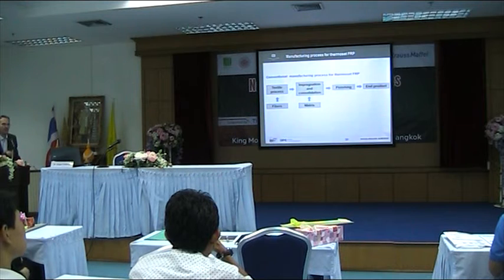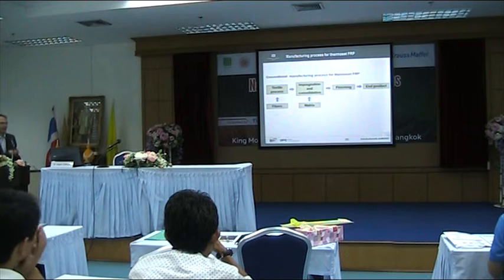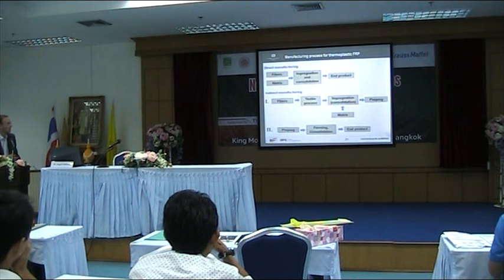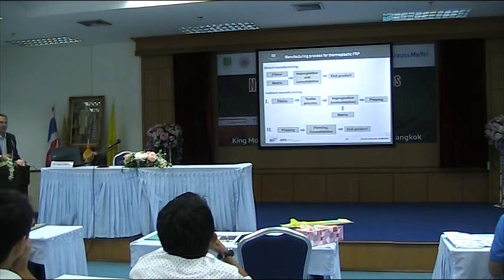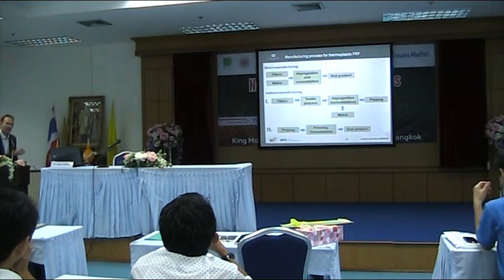For example, you have a weaving process or multi-axial laying process, or you have some warp knitting or knitting process. You get a textile pre-preg, then you bring the matrix inside. This you have in the liquid composite molding, like resin transfer molding, some finishing, and you have an end product. This is a typical line for a thermoset. But when you look at thermoplastic, it's much more complicated, and you have much more possibilities to deal with the matrix, with the fiber, and with the process.